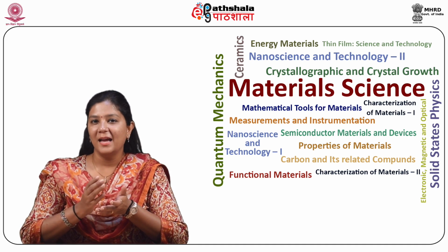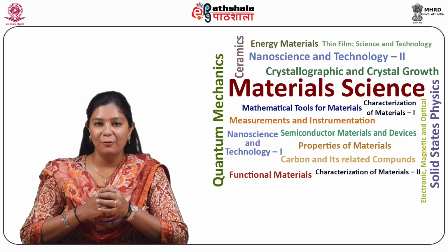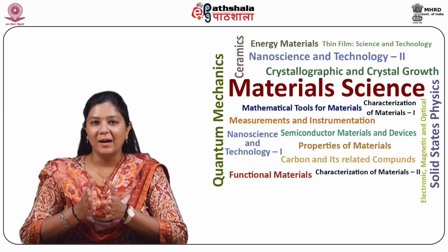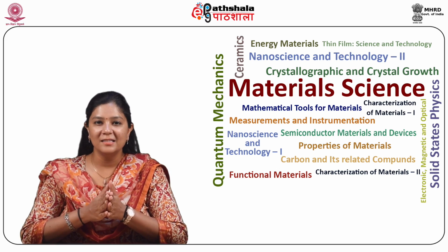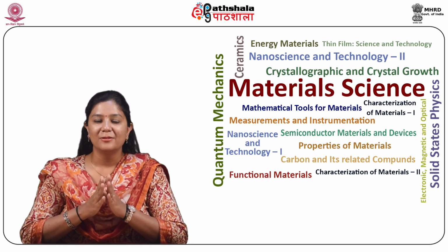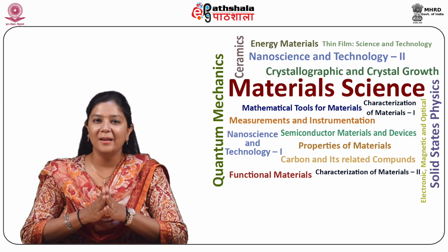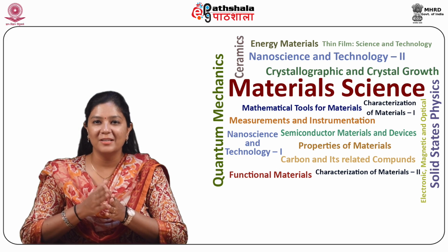It should be such that the activation overpotential at anode and mass transport overpotential at cathode are minimal. GDL should keep a balance between water flooding conditions, increase of mass transport resistance, hence loss in voltage, and water drying condition, where there is decrease of proton conductivity in membrane. So designing of thinner bipolar plates of low resistivity materials for excellent stack performance is the key to success of minimization of cost and higher efficiency as mentioned.